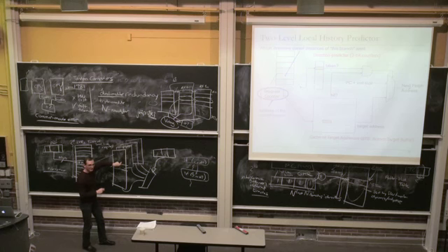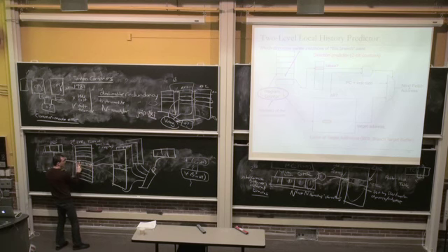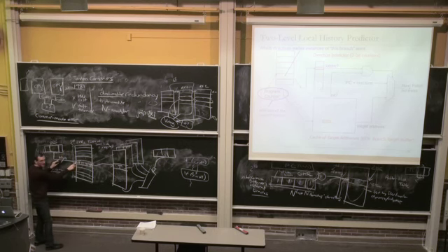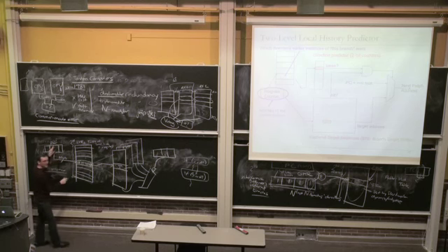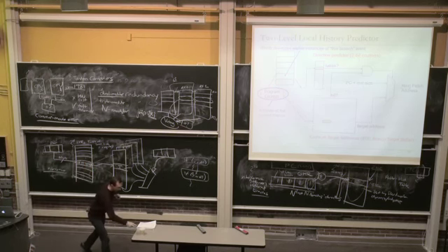Oh. Right? So you cannot put the counters here because you want to figure out whether you're taken or not taken based on the value of your history, not value of your PC. Right? If you put the counters here, then you associate the prediction with the PC, not the history. That's why you have two levels, right? That becomes one level. Yeah, because you want the PC across the history. Exactly.